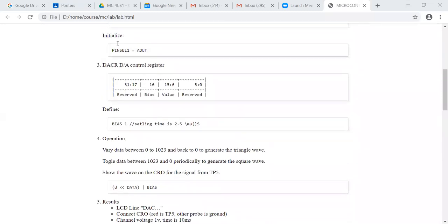Okay, so we have programmed the ports, only one port actually, and now we move on to programming the register on the device. The device in this case is the digital to analog conversion device, or a DAC it is called, and there is one register we need to program where we feed the value into the register, which is 10-bit wide. Actually it's a 10-bit DAC.